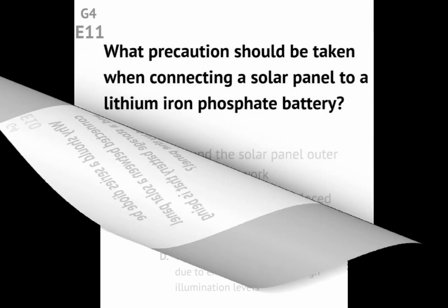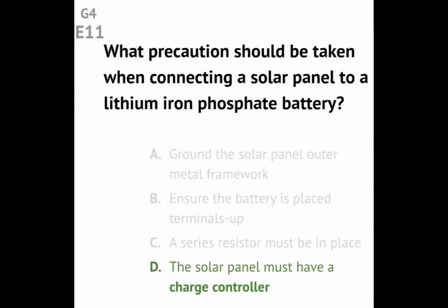Question G4E11. What precautions should be taken when connecting a solar panel to a lithium iron phosphate battery? Answer: the solar panel must have a charge controller.